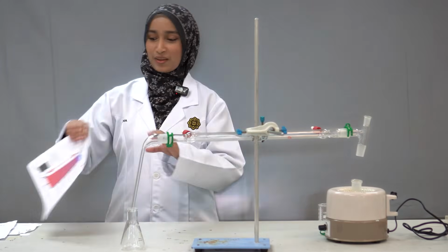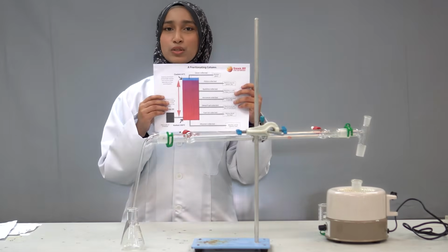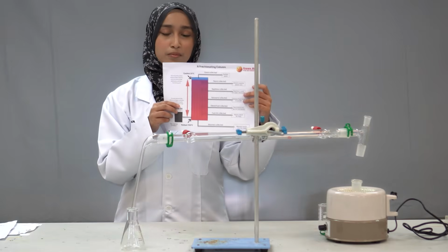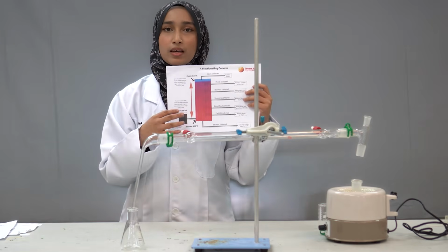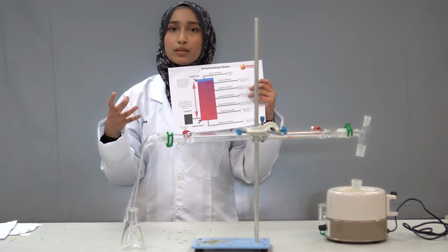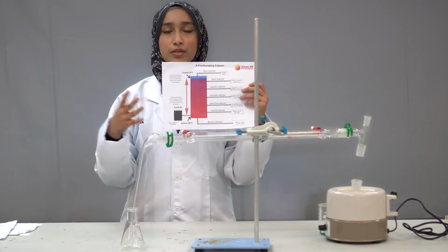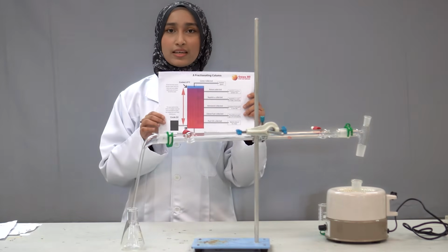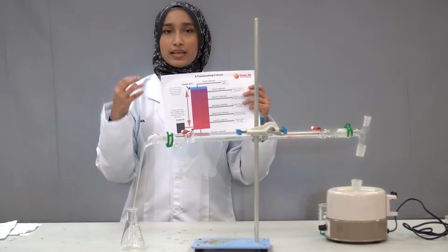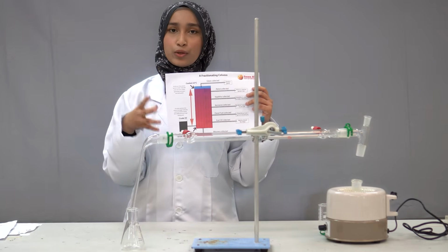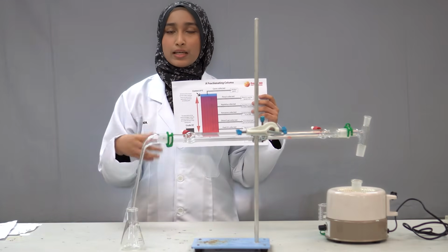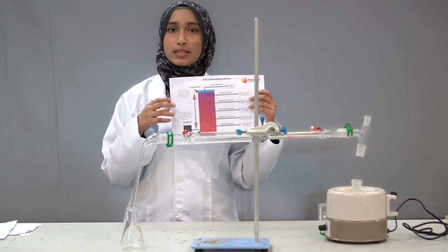So this oil will be fed into the distillation column, or distillation tower, or fractionating column, and will be separated into many layers. Each layer holds a different petroleum product, such as petrol, diesel, kerosene, naphtha, and many others. In this fractionating column, at the top of the column, it has smaller or less dense molecules which are more volatile, ignite easily, and have a lower boiling point, that will vaporize first when the crude oil is heated.